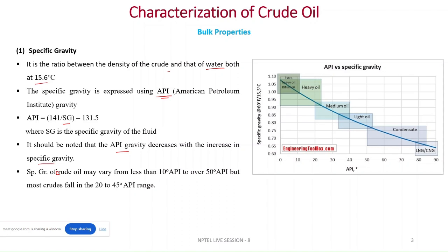Specific gravity is a ratio, right? But the main thing is it is the density with respect to water density. It is measured like that. So the specific gravity of the bitumen is higher, right? It is collected at the bottom of the distillation unit. So it has a higher specific gravity, and for this you can see that the API value is lowest.